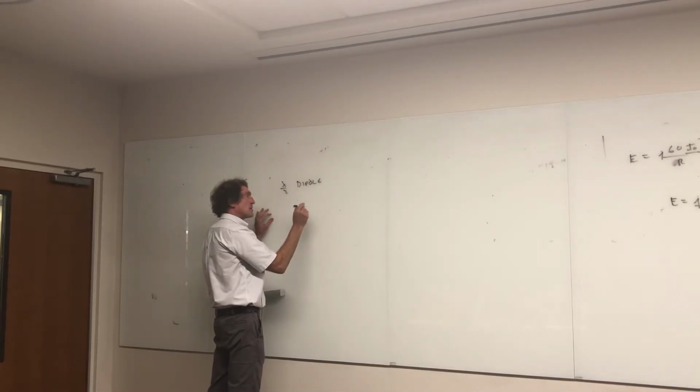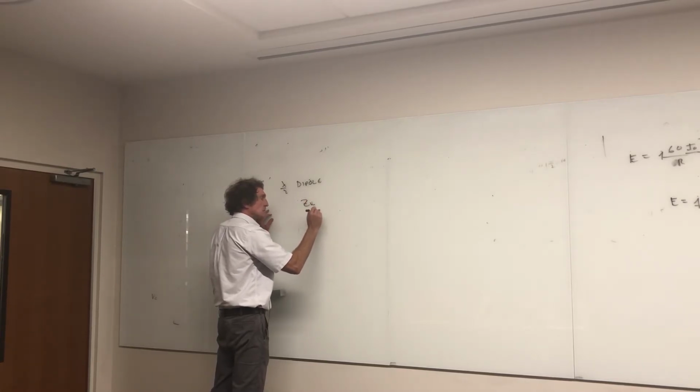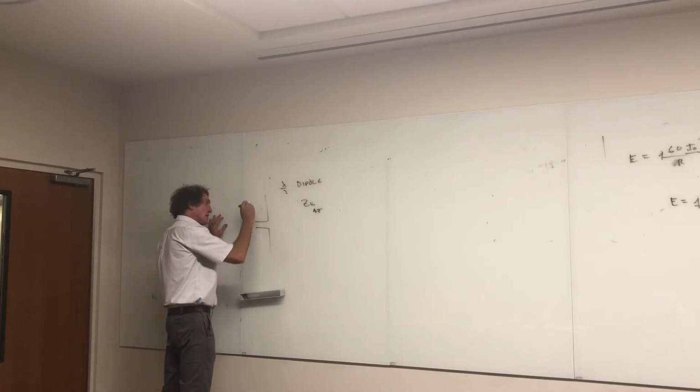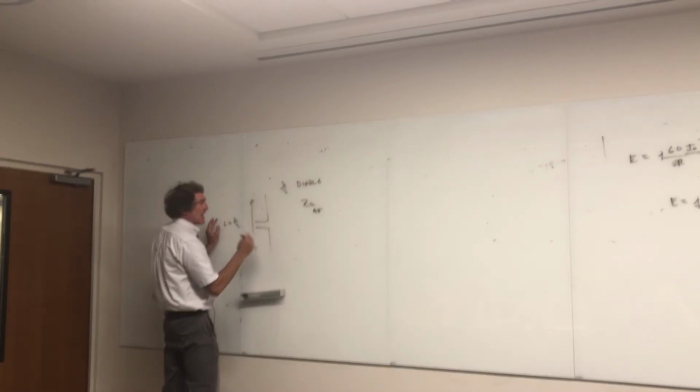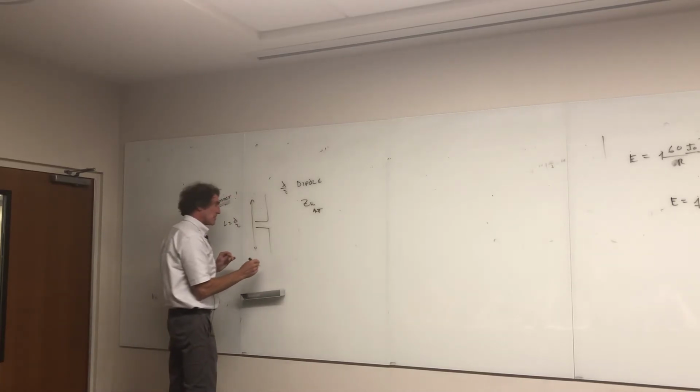You're going to find out that the input impedance, Zin, for the antenna, that's the input impedance to the antenna, means if you have an exact λ/2, L would be λ/2, and this means exact, so I better put down the word exact. It has to be exactly a λ/2 antenna.